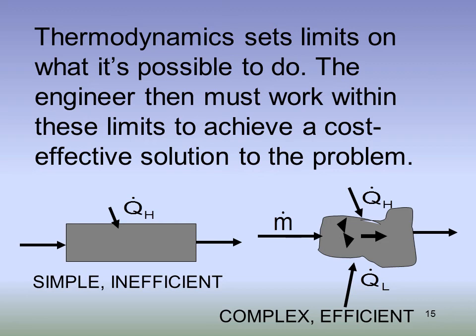Well, if you really approach it, you never get to complete reversibility, but if you did, it would cost a lot. So you're really balancing the operating cost of not being able to heat as much air with this heat exchanger against the capital cost of spending more on the equipment but being able to do more with it. So it's usually a cost-benefit tradeoff that engineers go for.